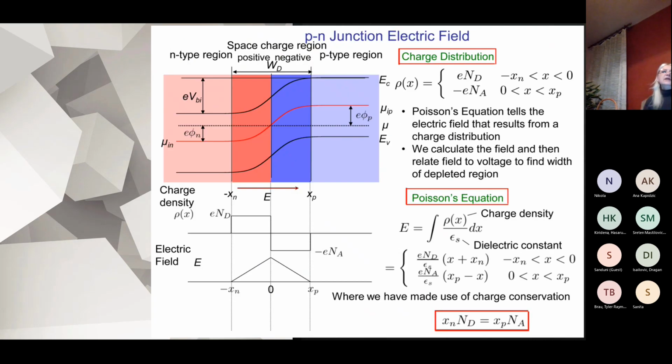And now, further, we try to calculate how big the thickness of the space charge region, or depletion zone, is. This is quite important because it will be much easier to follow what is happening with the charged species when we apply an electric field.